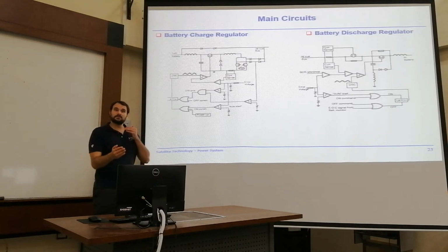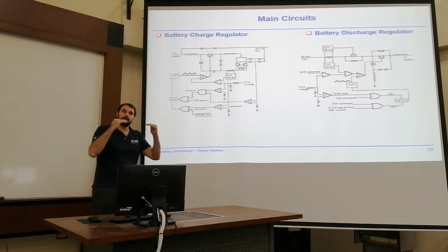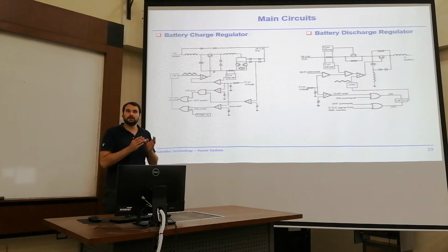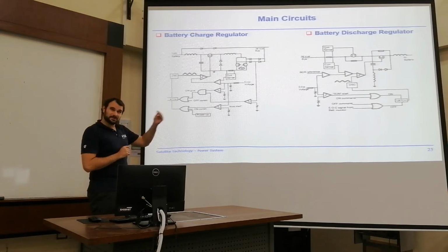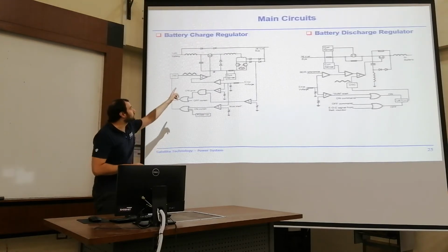By dynamically switching the coil on and off, you can decide where you want to land with your voltage level, simply by the duty cycle of on and off. And in order that the voltage doesn't drop to zero in those phases where you don't close the switch, you need this coil.